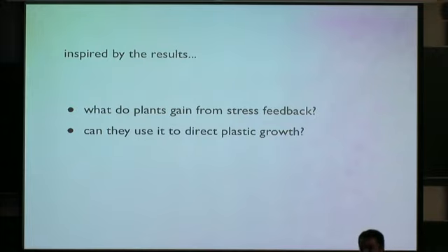Because elastic deformation is a tiny amount, maybe below 10%, maybe 6-7%. So this is not enough to create pattern formations. So we need to add a plastic growth model to our model.